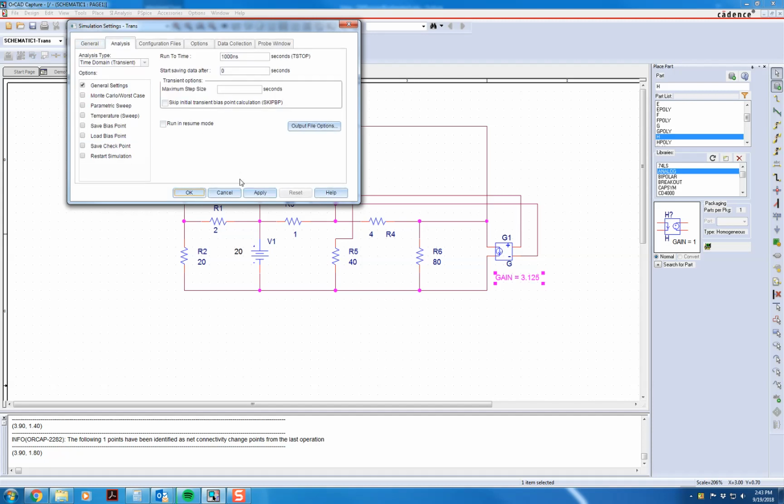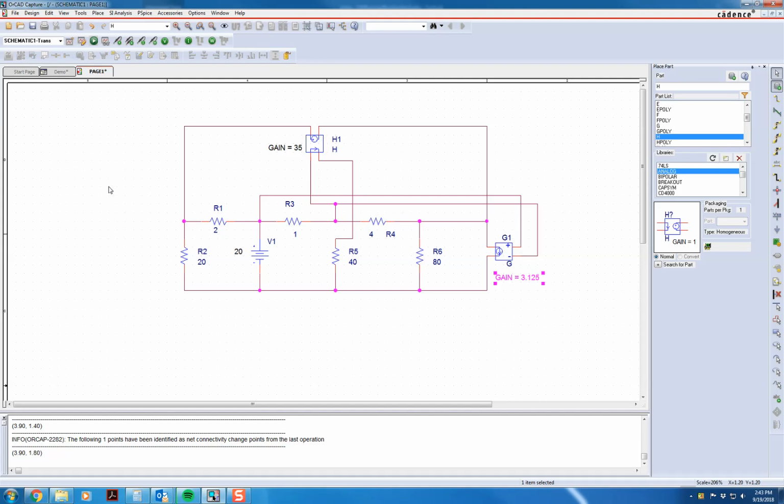Warnings reported. I'll let it finish running the simulation. And I even mentioned this on the first video. Hopefully you can identify what I have done wrong here. You can kind of see it right here. I don't have a ground. You always have to have a ground, but it's still trying to simulate right now, so it's still communicating with the server here.